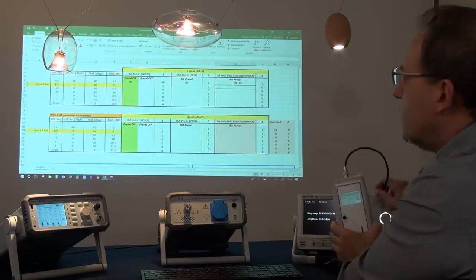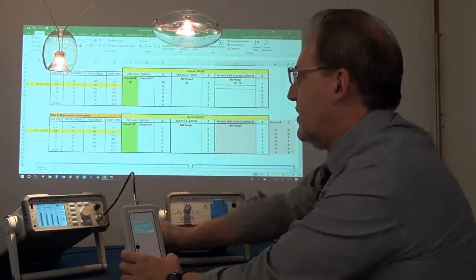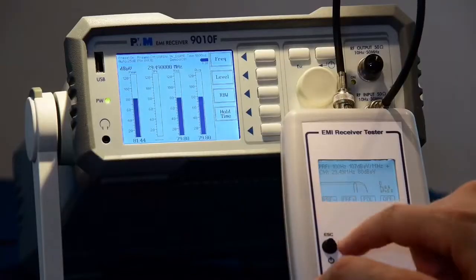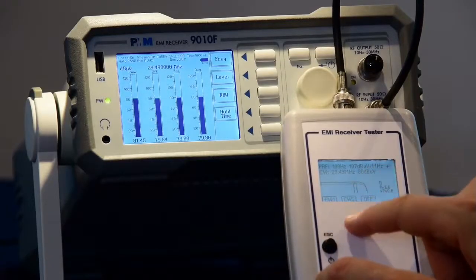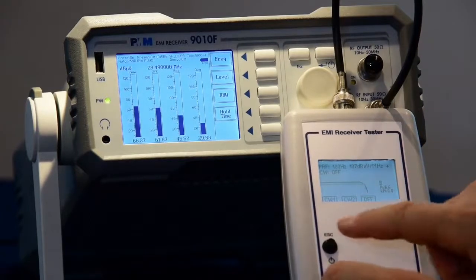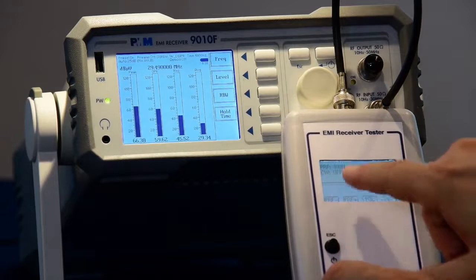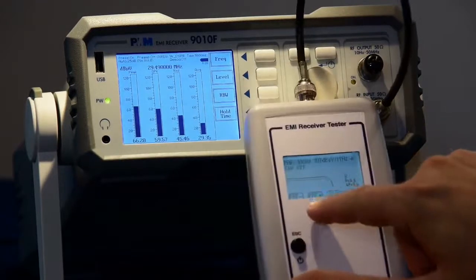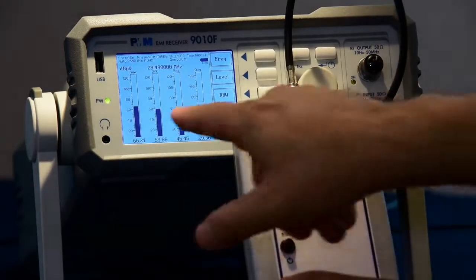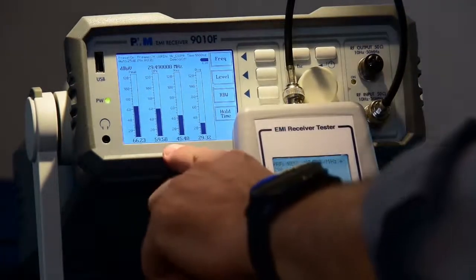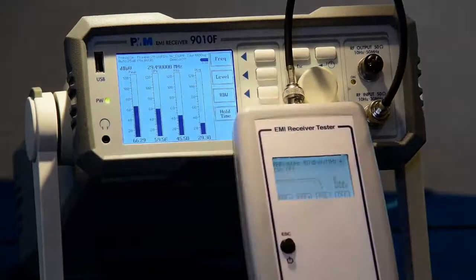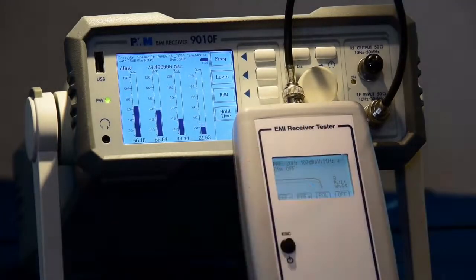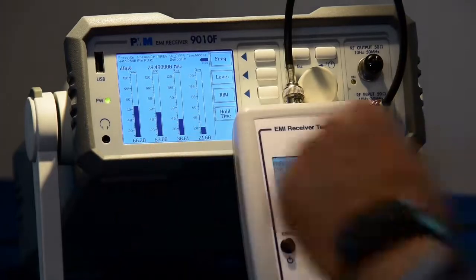Okay, now we move back to the full compliant receiver, and we are going to set now, first of all, we delete the carrier wave, so we set the carrier wave off. Then we go to the pulses and we start measuring the 100 Hz pulse repetition frequency. So you see here is 100 Hz, and on the receiver we can read exactly 59.58, so is 60. Let's say 60. Then we can reduce this value to 20 Hz pulse repetition frequency, and we can read 53.